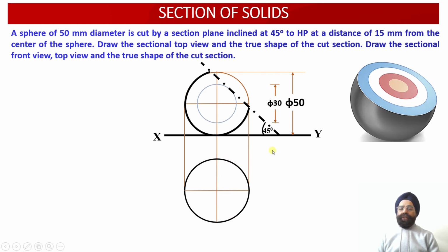So what we are going to do, just like as it is shown over here, we are going to use the principle of slicing over here. So we know that there are 2 points which are available corresponding to these extreme points which will be available in the top view projections over here. One point will be projected here. Another point will be projected onto this diameter over here.